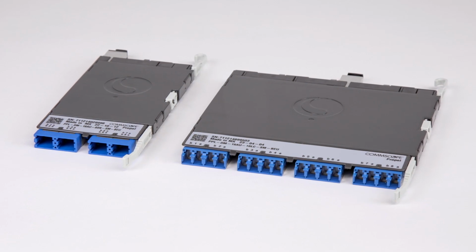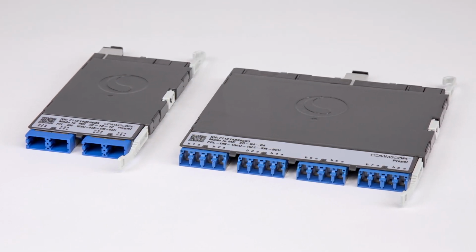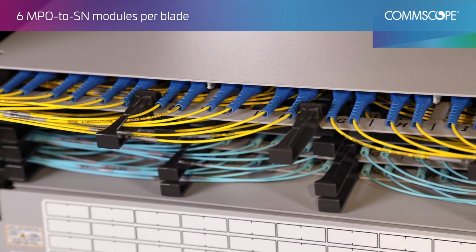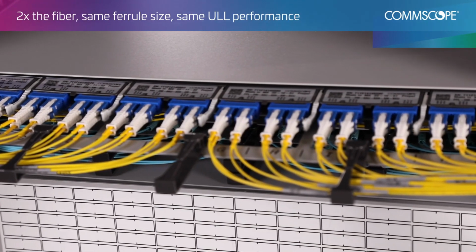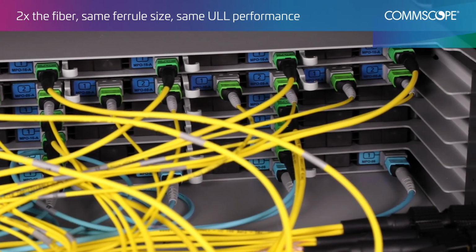The same process can be followed to swap out MPO 16 to LC modules with MPO 16 to SN modules. Because the MPO to SN module is half the width of the MPO 16 to LC module, you can fit 6 on each blade. That means you can double the fiber count of each blade and use the same size proven ferrule as the LC duplex connector.